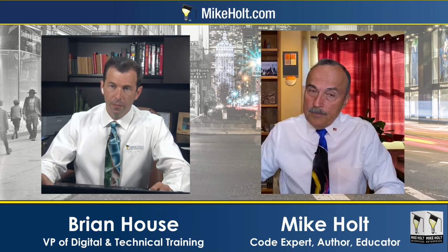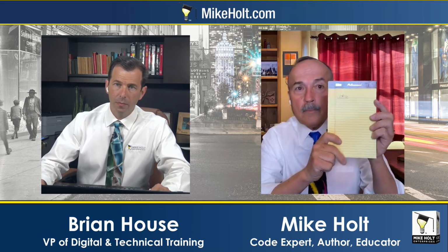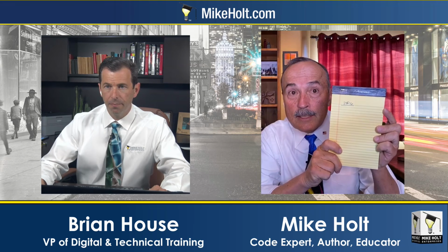Okay, these are the kind of things. Now, tell you what I'm going to do, Brian. I made a note. 250.6, I will cover objectionable current. But hopefully, guys, don't try to use words, understand electrical theory. We don't have the neutral in parallel with the equipment grounding conductor, which means you do what? You have to bond it at the service. Done.